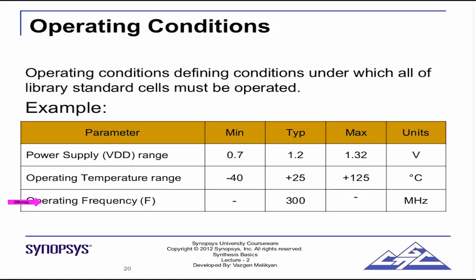And if it gets a power supply which is lower than VDD, it will again go slower. Now let's say it gets an operating temperature of 125, it will still become slower, because rising temperature means more delay. So what we define is corners or operating conditions, and we try to capture the full limit of variation.